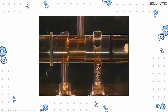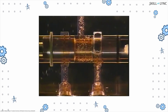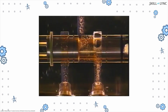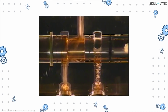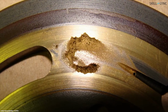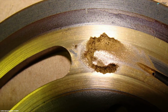In a hydraulic system, the fluid is subjected to various conditions like large pressure and temperature variations, turbulence, and contamination of particulates. Thus, a hydraulic fluid should be stable chemically as well as physically to ensure usage for long time periods. Moreover, the compatibility of the hydraulic fluid with the system is a must. Otherwise, the hydraulic fluid may damage the parts by reacting with them, thus losing its functional efficiency.